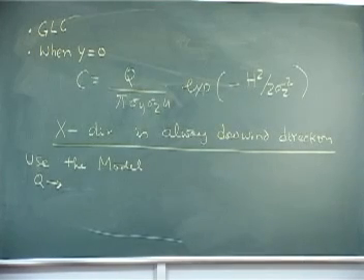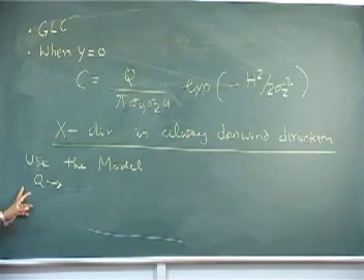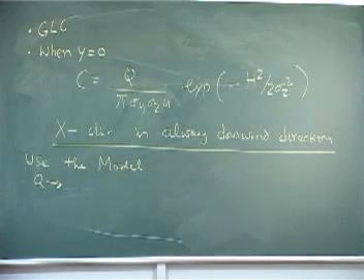From the emission inventory, you remember we worked out the emission inventory. This is the source, a power plant burning so much coal, with the sulfur content of this one, and that coal consumption is so many tons per day. So what will be the sulfur dioxide emission? You did that in one of the examples, and you found that the emission of sulfur dioxide will be 19 times the S, that is the sulfur content, times your tons per day of the coal used, and things like that. So that Q can be estimated, or most of the time it will be given to you, or you can estimate it given the data.